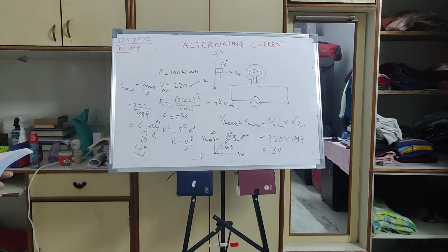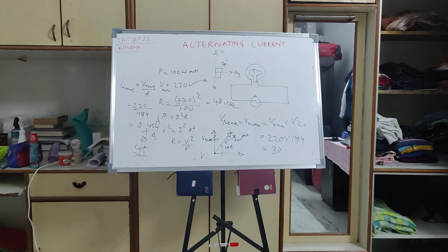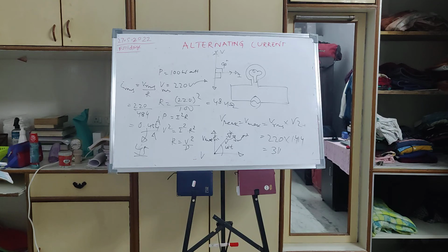So in a capacitive or RC circuit, voltage will lag, and in an inductive or LR circuit, voltage will lead. But for LRC it depends on the relative magnitude. The generalized equation for the phase angle is tan inverse of XC minus XL by R for the LRC circuit.